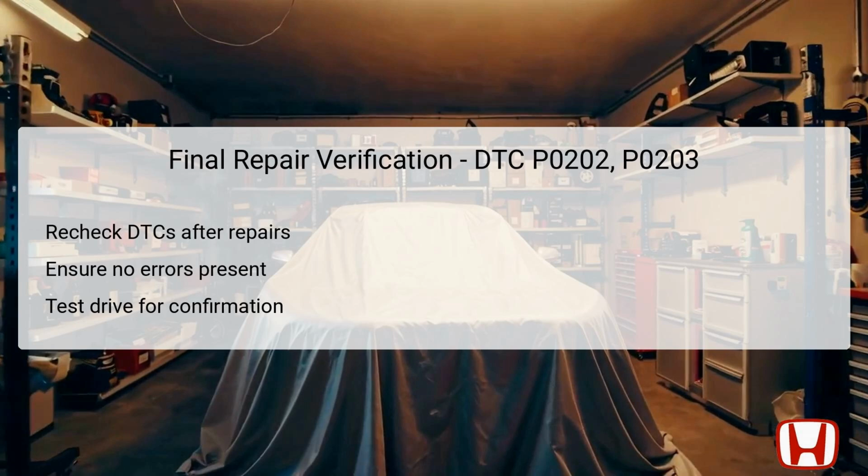If DTCs are cleared and do not return, ensure to perform a test drive to observe engine performance under real driving conditions. Monitor for any signs of issues such as misfires or poor acceleration to confirm that all repairs have rectified the underlying problems effectively. This final verification solidifies the repair's success, ensuring the vehicle operates seamlessly moving forward.